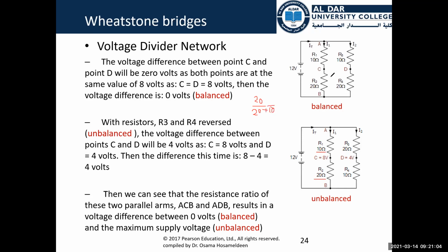I'm calculating the voltage here. It is 20 over 10 plus 20 multiplied by 12. It should be 8 because it is 2/3 of 12. Okay, it's not an error. I just got confused because we have 10 and 20. So for 20 it will be 8 volts.